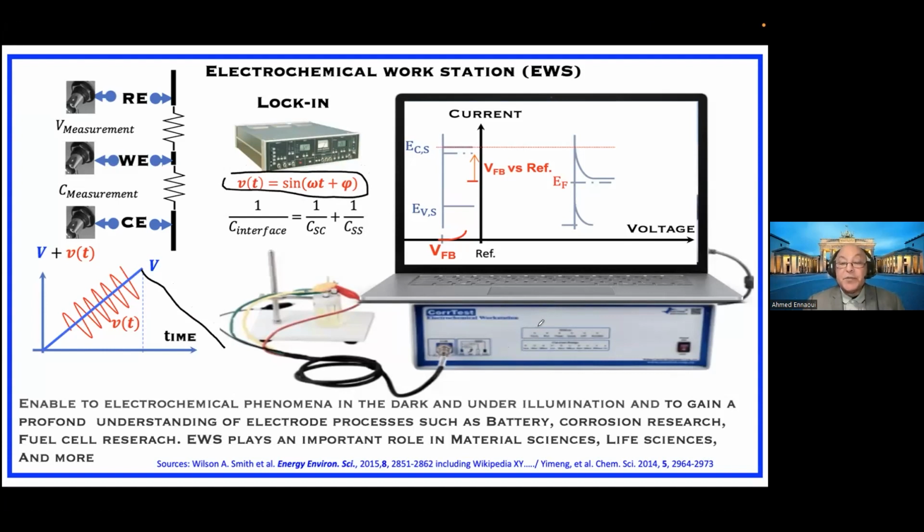Actually, the potentiostat contains a generator for this sinusoidal wave, but you can also buy what we call a lock-in amplifier, outside your potentiostat, to analyze your response and to measure your capacitance.